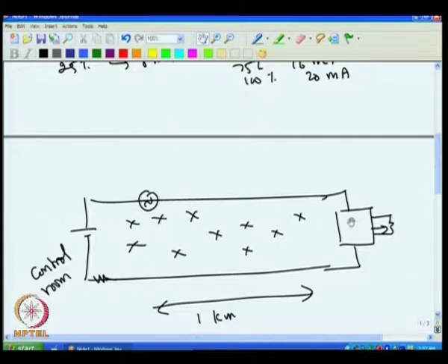And then this unit's minimum current is 4 milliampere, as we said it is a 4-20 milliampere system. So, when the system is at the lowest, the current in this will be 4 milliampere. Obviously this should not consume more than 4 milliampere, and whatever current it consumes should be constant against temperature and other parameter variations, so that only this variation changes the current.